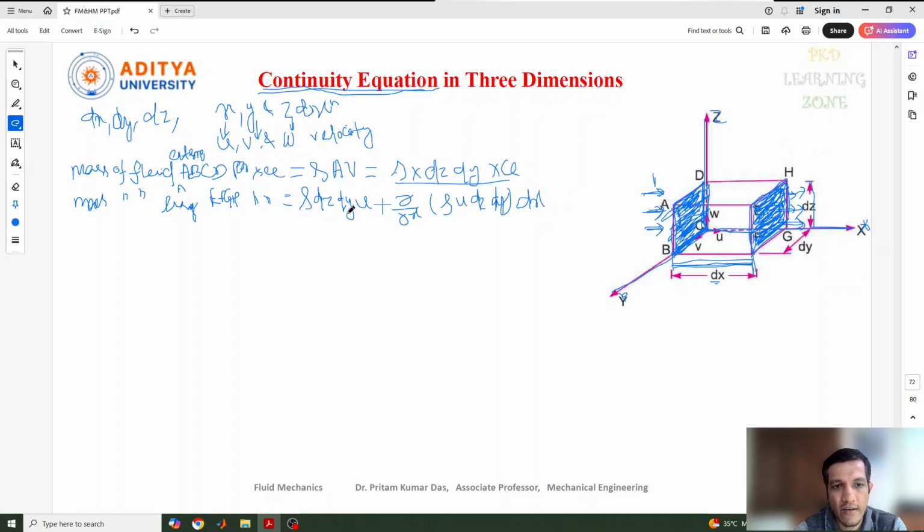This is the mass flow rate which already entered at the surface. Again, the same mass flow needs to cross this length. So we write the derivative of the same mass flow rate which entered here, with a length of dx, inside a square bracket. These two things are the mass of fluid entered and the mass of fluid exiting at these two surfaces.